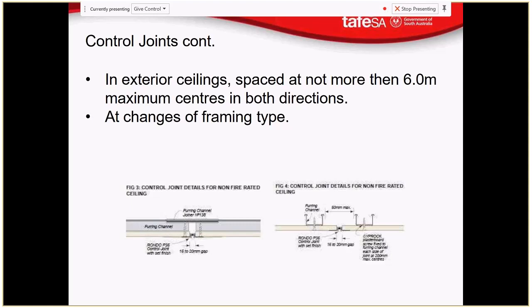When we use such a system with these hollow concrete panels, and then we finish over the top, because there's flexibility in the structure, but not really flexibility in the finish that we put over the top, we will have to provide control joints in that floor. And so we want the floor to crack in the specified places where we want that to crack.